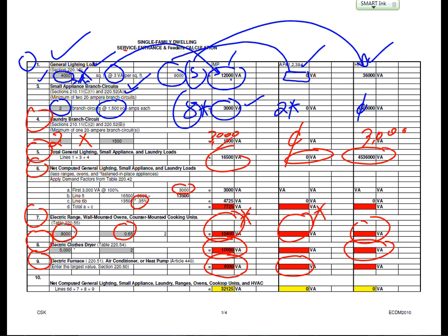Can you guys see what I'm doing? I'm accounting for every single electrical load fed from these panels. Who cares? That's how we size that panel that you're looking at here, and the main panel and the feeders. Ultimately, guys, you as a designer, they're going to come to you and say, is this going to be a 400 amp panel or a 6,000 amp panel? How are you going to accommodate? Here's the step-by-step how you do it in an Excel format.